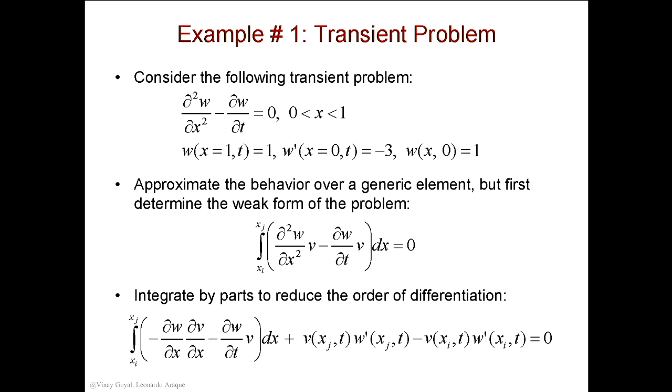Okay. And so the next step is that this is still the strong form, but in a weighted residual format. And we've already learned that in this format, we still want to reduce the continuity requirements so that we only have to satisfy the essential boundary conditions of the problem. To do that, from now on, I'm no longer showing you how to integrate by parts. Everybody here should be able to do it almost by memory.